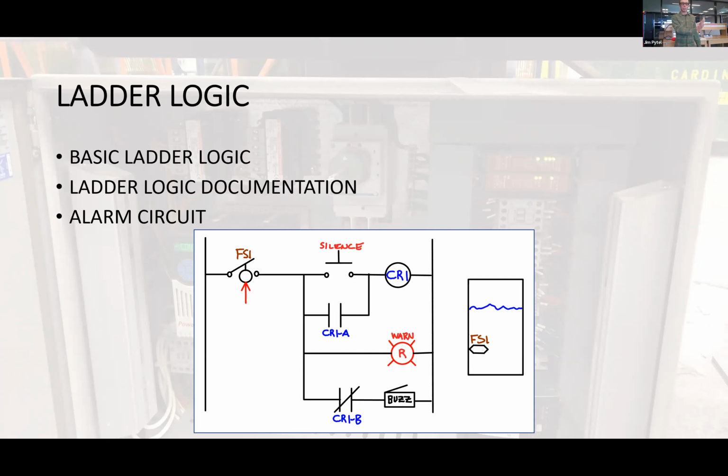Starting from one end of the rung, left to right, work only on that rung. Move down to the next rung. Left to right, work on that rung, move down a rung. So again, this is the first thing they've wired up. It's very important that you as an instructor verify that they're hooking everything up correctly, and I basically do a line by line check.